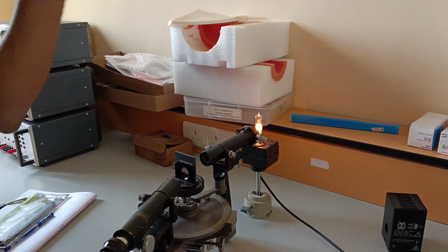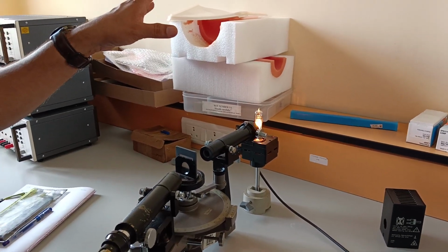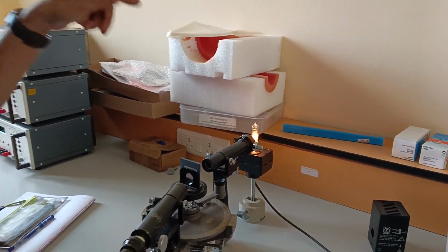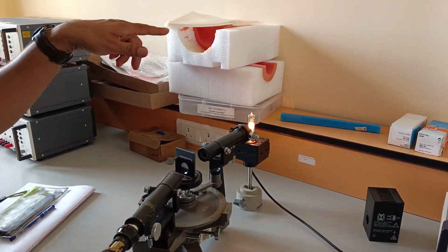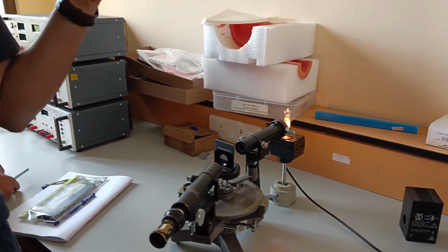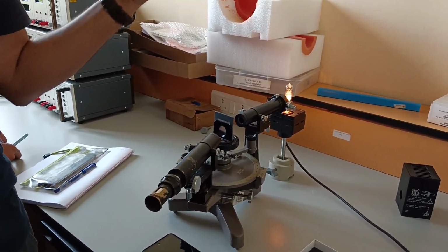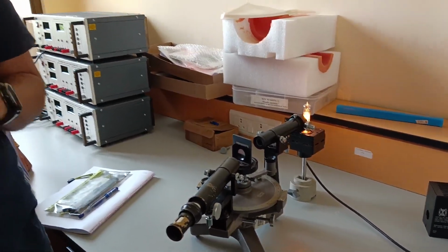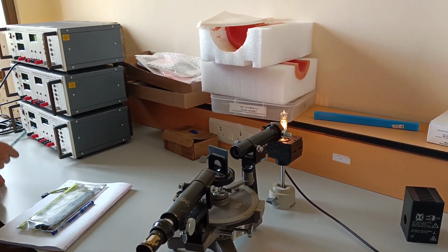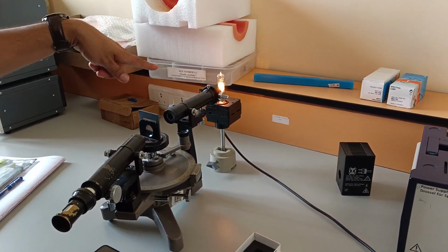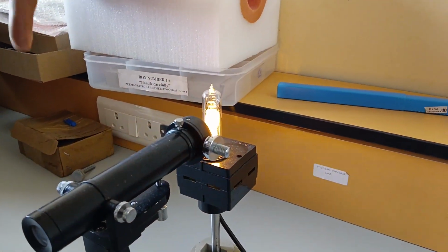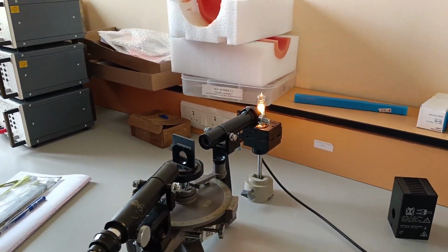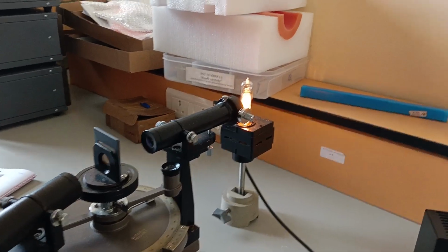Do not touch it by hand. If you touch, your skin will stay there. I am not joking. Whatever happens to your hand is a different thing. You will not die, don't worry. But that will spoil the lamp because the skin will stay there and it will burn and get carbonized and become brown, and then whenever you switch on the lamp, more heat will be deposited there and at one point it will crack. Okay, so we don't want that. That's why you see it is double walled. You must have noticed there is a glass inside the glass. Both are quartz. But don't bank on it.